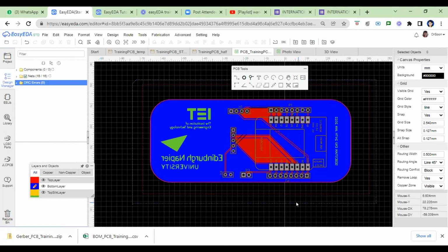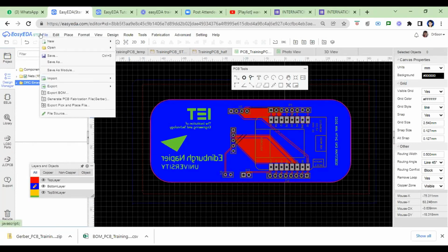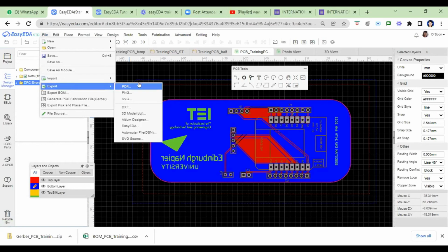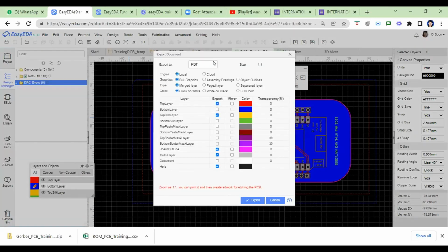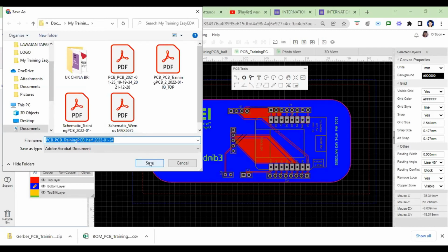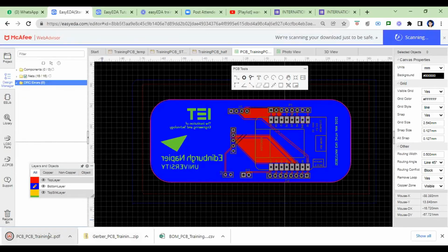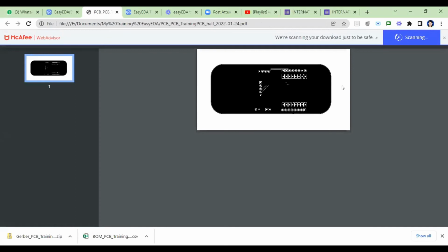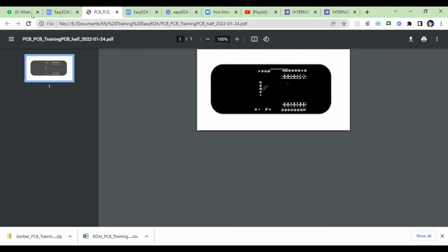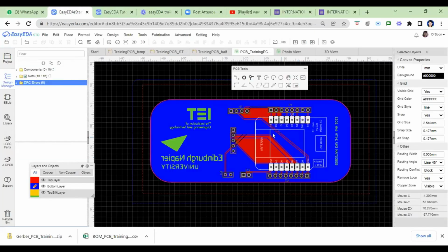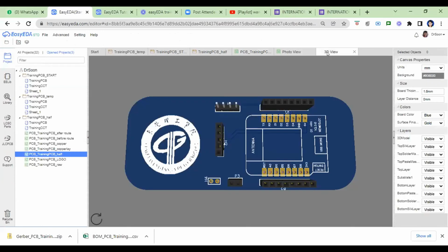Oh, finish. Okay, now you want to present the project, I mean these files, in your report, so you can export in PDF. All right, so anything that you want, I mean the PCB design, the top layer, bottom layer, you can actually export it. Okay, export it to a folder, let's say PCB. Then I open up this file and show you. Okay, so that contains, maybe I didn't click the top button. All right, so that will give you the file for the PCB, right? So it's not that beautiful, but I think it's better that you do the screen capture, then it gives you a better representation. All right, okay, finish.